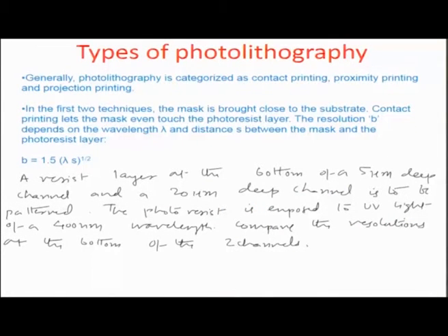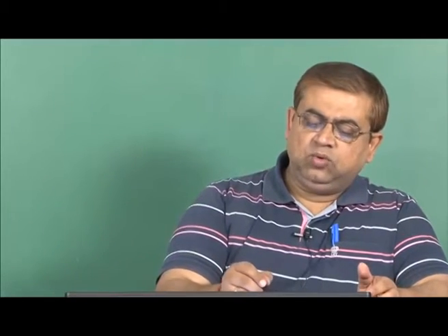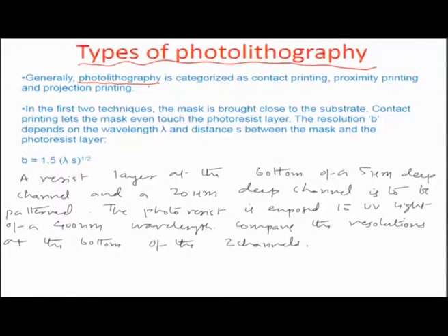The other important aspect which I would like to now deal with is photolithography, which is the way in which patterning is provided onto any surface, and then this can be coupled with a variety of processes like etching and deposition to make metal patterns and small etches within the surfaces. Generally, before looking at the various classes of photolithography, let's look at what this process is all about.